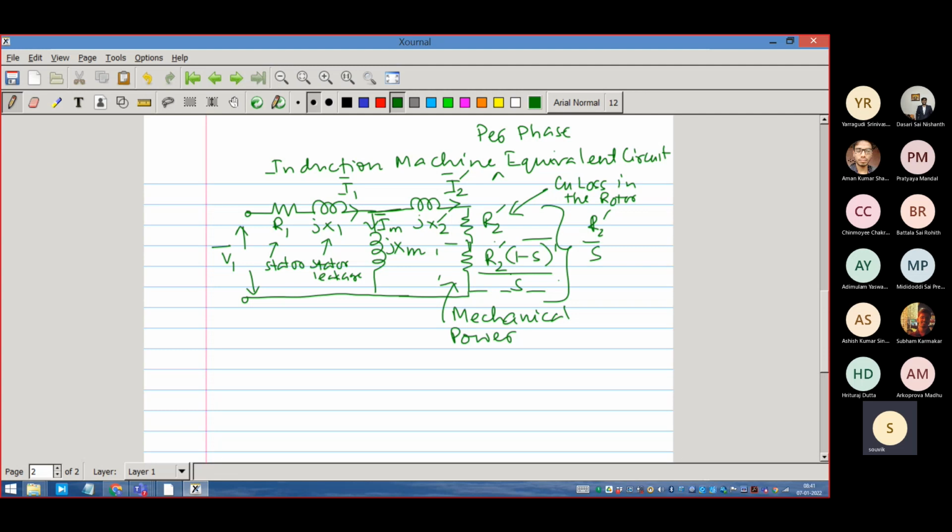It may also represent the physics of power conversion from mechanical to electrical, where the S term becomes negative, because the machine then runs at a higher speed than the synchronous speed. That omega synchronous becomes less than omega rotor, so it becomes a negative thing. That negative thing means that power is reversed. That means the power will be going from the mechanical side to the electrical side.